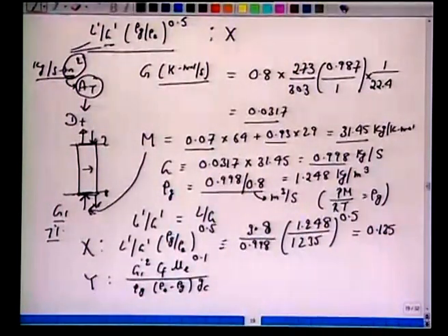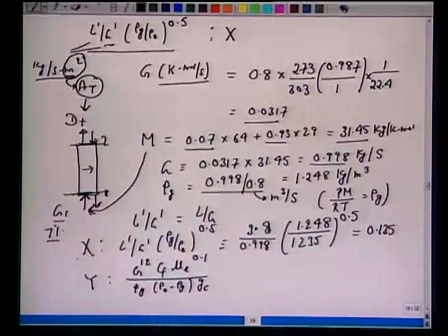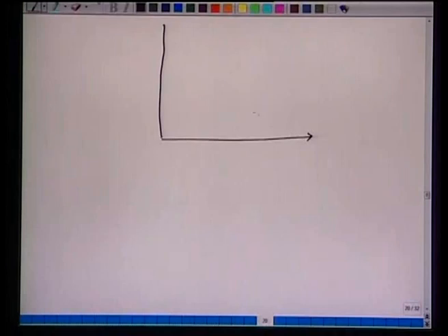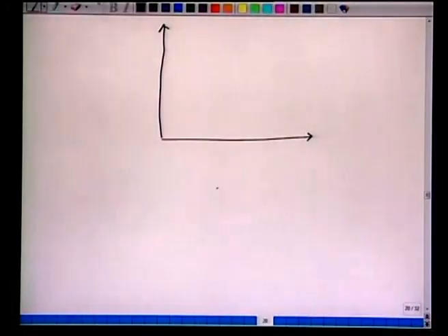So this also involves G prime. Okay. So now we are supposed to evaluate this quantity G prime from here. We know the ratio of L prime over G prime from the x axis. So now we can go back to that plot. So take the plot from Treybal or from some textbook.